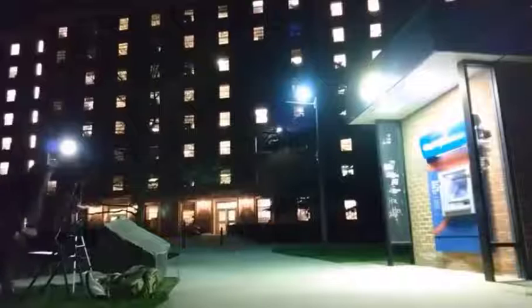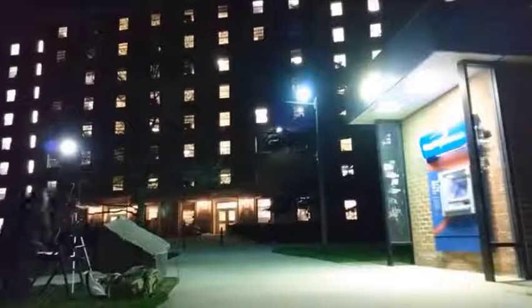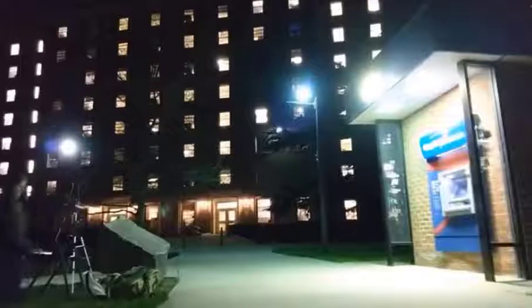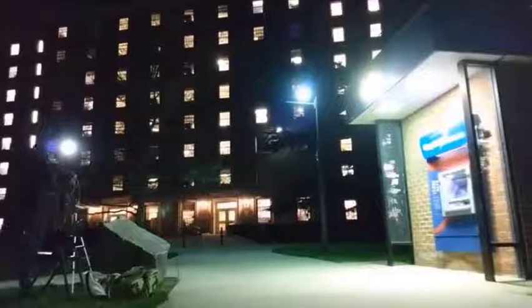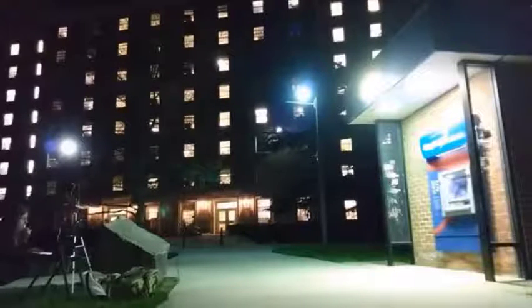At this point, I realized I was mapping at a range of slightly over 10 feet, which was too far away for the camera to detect the laser line pixels moving across the screen. I began remapping at a closer distance and was able to achieve a 3D point cloud that looked like the side of the ATM. Unfortunately, I was never able to get a 3D point cloud of the front face of the ATM as there was far too much ambient light that could not be blocked out.